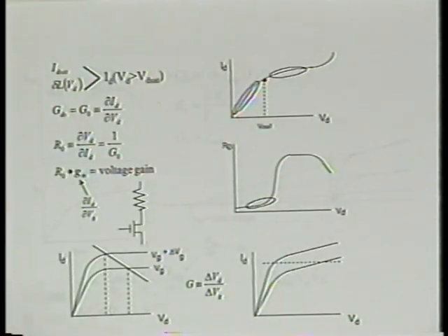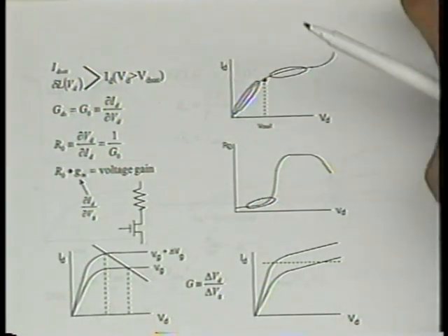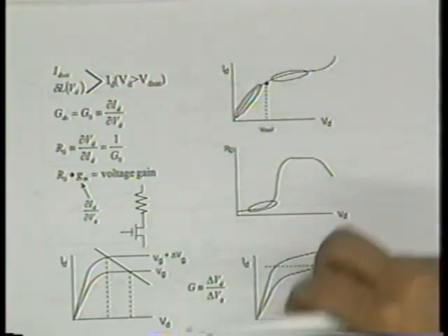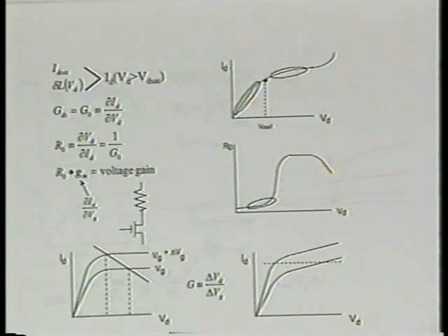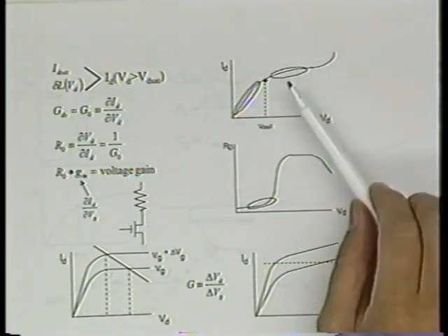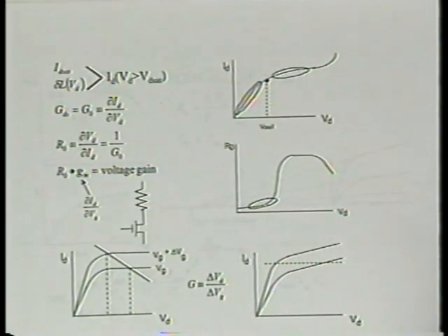Okay. Now you see the full model, but we all agree that we don't like complicated equations, and arcsinh is still a little bit too complicated for us to use. So we're going to give you a simpler form. The simpler form is not in the form of delta L, because no one really wants delta L. I mean, of course, it may be nice, but what we really want is this R out, this output conductance or output resistance. Let me first introduce to you this quantity called R out, and then we'll try to give you a simplified form for R out directly, right, rather than delta L.